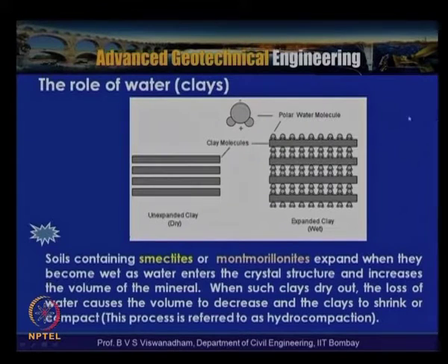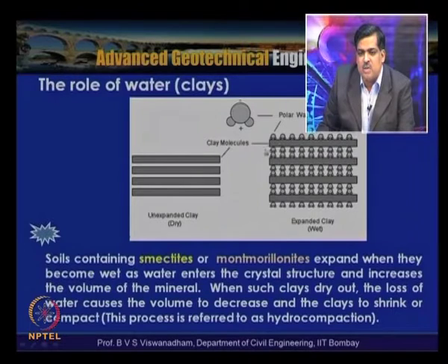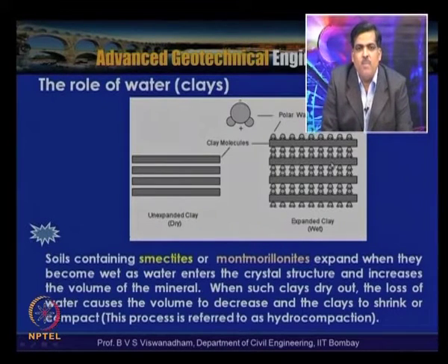When the polar water molecules come in contact with these platelet particles, the water accumulates between the particles or platelets, and it will form a state like expanded clay. So, this is in the dry state and this is in the wet state. At the same time, when this water evaporates because of exposure to temperature, the clay is subjected to shrinkage, which for this type of soils is also called hydrocompaction.